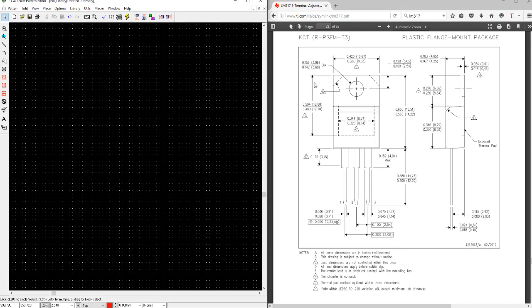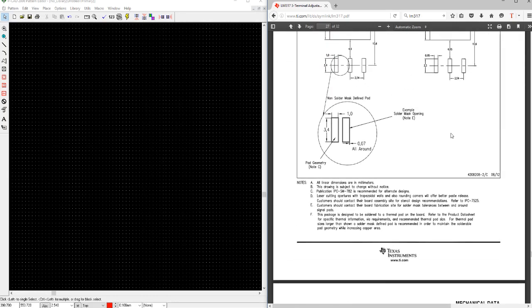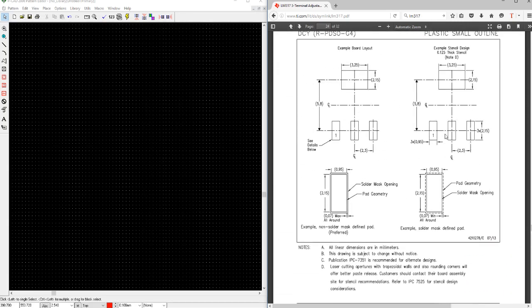Now, typically from this data sheet, you can see that they give you both values. The smaller value that you see here in front is the inch value. If we want to convert inch to mils, we multiply it by 1,000. So 0.142 inch or 142 mils. And that equates to 3.6 millimeters. So whenever you see a data sheet, you will find usually, if you scroll up, they should give you a clear indication. Let's just quickly have a look.